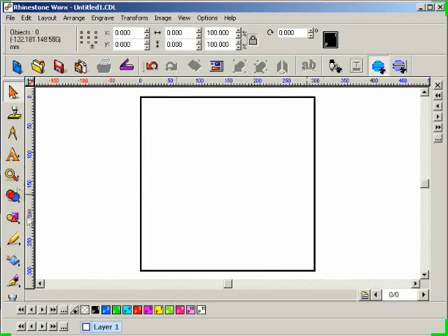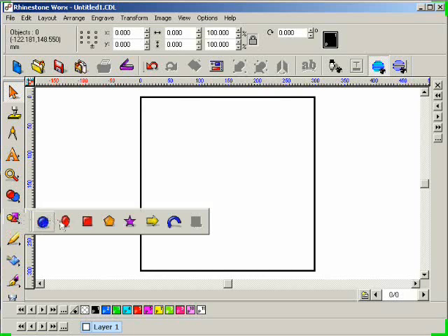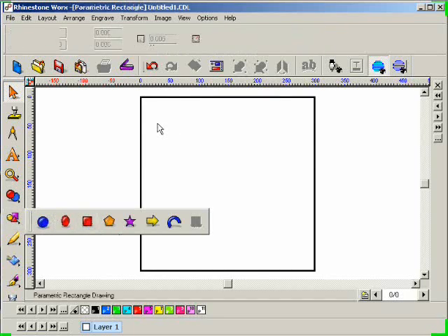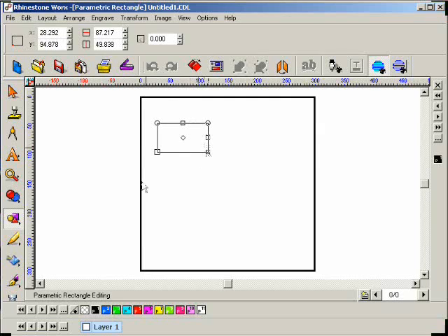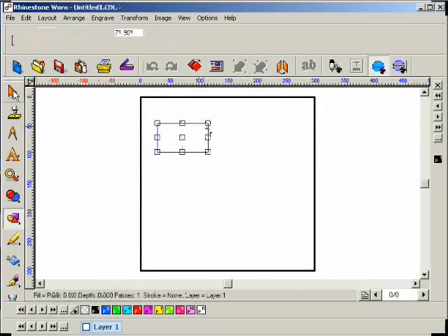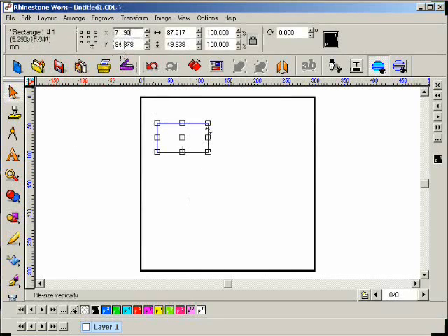Okay. Anything across the top that I need to know, or the general function of the information I get when I'm working with something? Well, as an example here, if I click on my rectangle tool and I'm holding down my left mouse key and I'm clicking and dragging to generate this rectangle. Now, if I click on the select tool, you'll notice up here that there's a horizontal position and a vertical position value. And that value is being generated based on this tic-tac-toe-like looking box here.